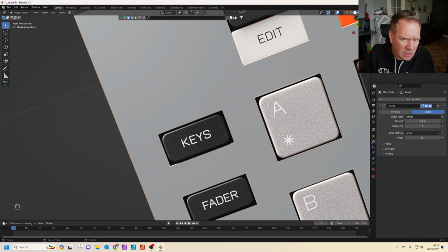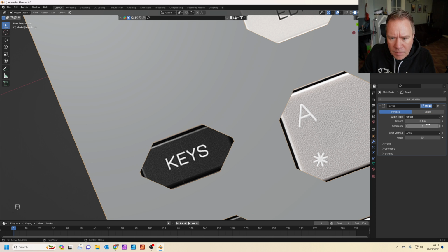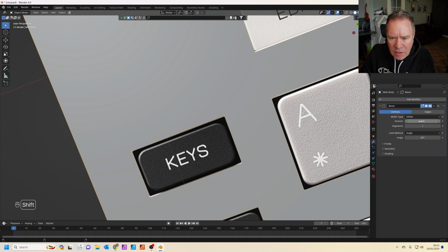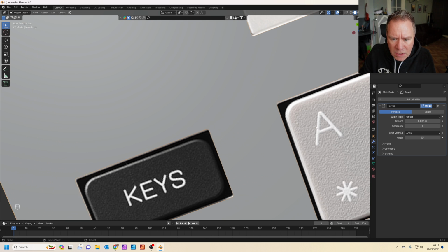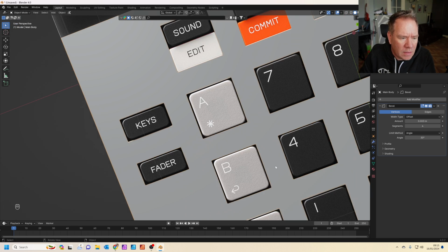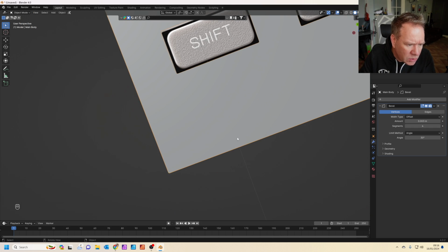It's just going to be a very subtle bevel, just to take a tiny radius off these corners. So we're going to bevel the vertices, not that much. You can hold down Shift to get a finer adjustment on this. Like I say, we're just taking the very tiny corner of these. Let's add a few segments in, maybe 4 segments should be enough. Okay, that just gives a little bit of extra polish to the corners of the model.